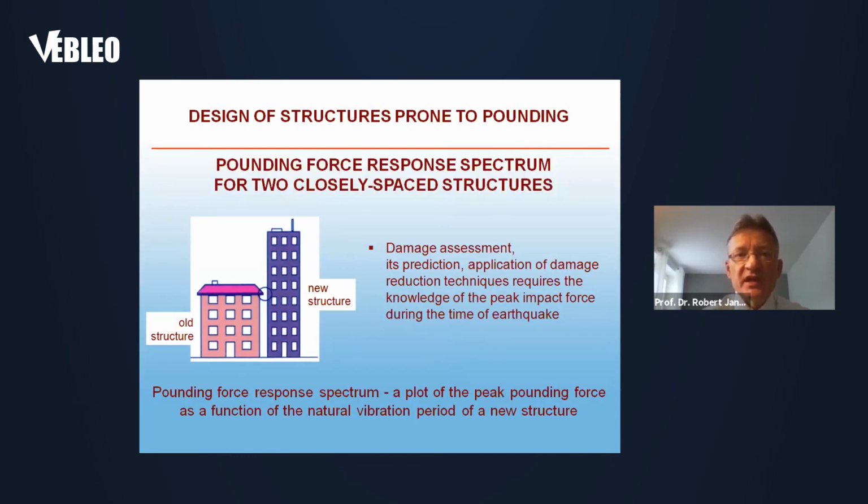Let me now say a few words about the design of structures which are prone to pounding. Firstly, in order to make the damage assessment or its prediction, and also to apply any damage reduction techniques, we need to know how large the pounding force is during the earthquake. For this purpose, we can use the idea called the pounding force response spectrum.